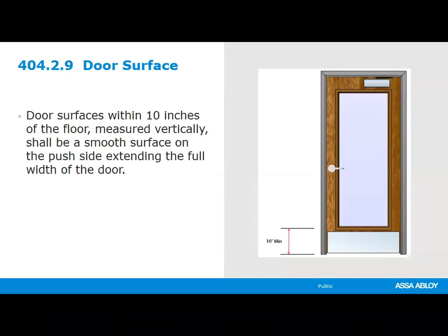There's a question regarding ADA height for pull handles. If the pull handle is large, does the entire handle need to be within the 48-inch height? No. Sometimes you'll have a pull handle that's full height of the door, and that's fine because the range is between 34 and 48, the part that you need to grasp. You're not going to grasp the top of the door unless maybe you're a Dallas Mavericks basketball player or something like that. But good question. As long as the handle is large enough to be within that 34, no higher than 48 inches for anybody to use, then it would be okay.